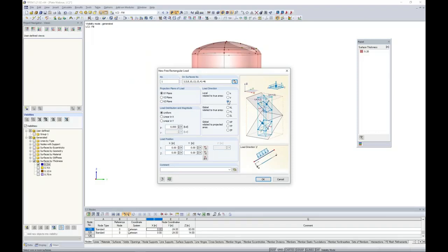So again, this is why it's very important for those local axes. If the z-axis was different for each surface, it's very difficult to apply a load all at once. We want this to actually be in the YZ plane. So we can reference these. It's kind of into the plane. And we want it to vary in the Z direction.